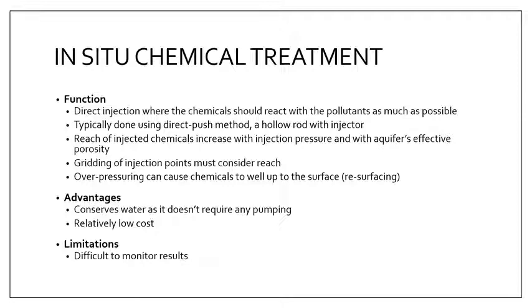You also have your sorption processes, wherein your contaminants just stick to the soil grains. You also have your decay processes, which involve the chemical and biochemical reactions within the soil. So it might be difficult to quantify or measure if the chemicals that you introduced in the site were actually the ones that were working on the contaminant, as opposed to natural attenuation processes.